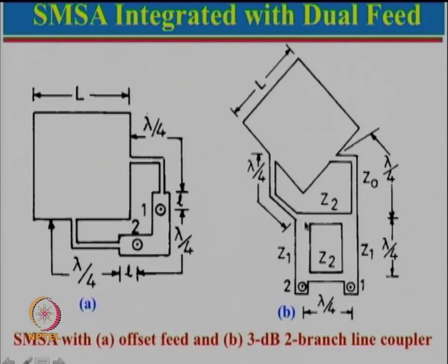So, then the question comes, why is this not becoming 0? The reason for that is we have taken a larger width here. So, larger width means larger power goes here, a fraction of the power goes here. Out of this fraction of power, some fraction is going, and then a fraction of that is going. So, it is like this is also minus 90 degree phase delay, this here is minus 270 degree phase delay, which is plus 90 degree. So, even though the two paths have opposite phase, cancellation does not happen fully. Think this way, suppose this is coming out to be a number, let us say 0.8, and if this is coming out to be let us say 0.1, so that will be 0.7.